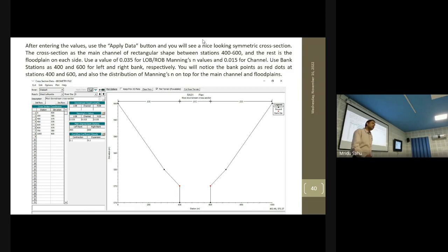But we are at the most downstream end. There is no cross section further. Next point is not there. So in this particular station, station 0, no need to feed these data sets because we don't have anything. From the most downstream location, we don't have any cross section next. That is the last point. So don't fill any data here.